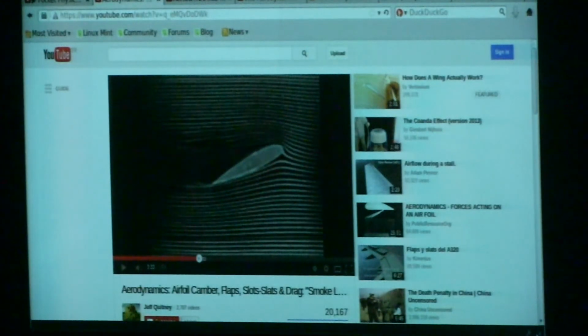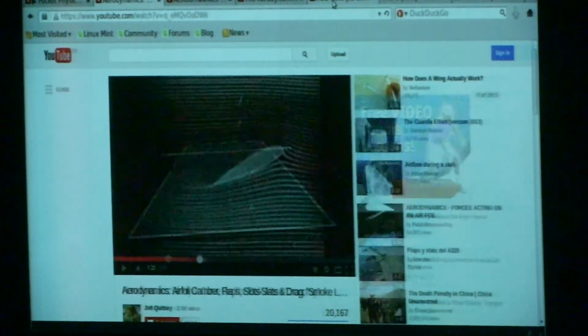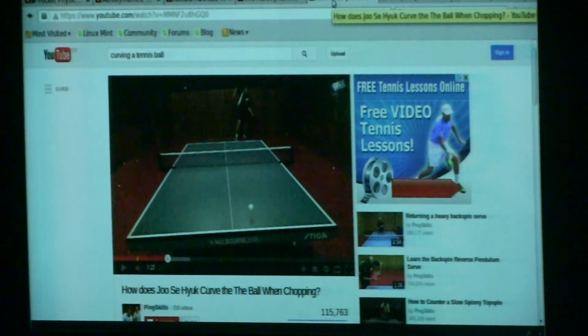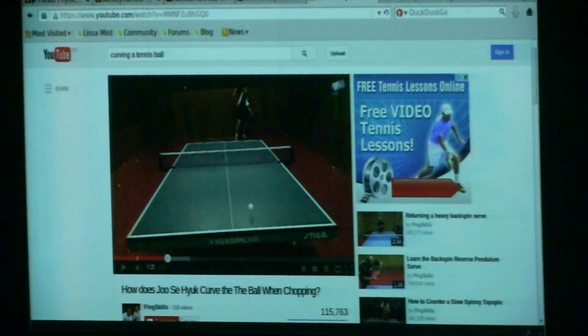So we have these two effects. One is the change in the momentum of the air that is causing the wing to move upward. The other one is this lifting effect due to Bernoulli's equation. The speed of the air is larger over here, so the pressure here is smaller than the pressure over there. So these two effects help to lift the plane as it flies. Is there a question? Okay, so now the same principle also holds here, when the ball takes a curve.